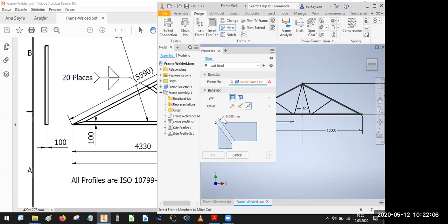Also for welding properties, the welded assemblies have some gaps needed for welding, because welding is a process with heat, and heat causes expansion of our profiles, and this expansion results in relief stress on our frames.